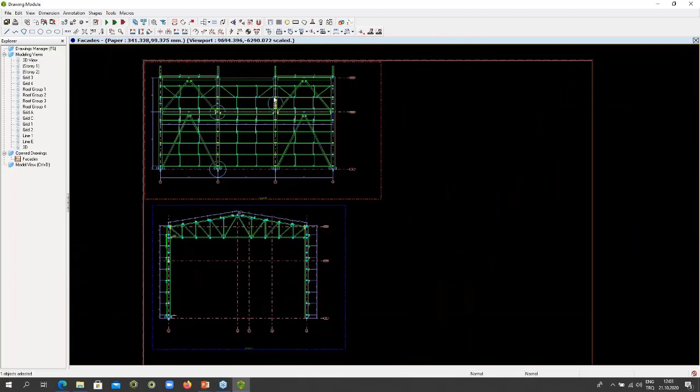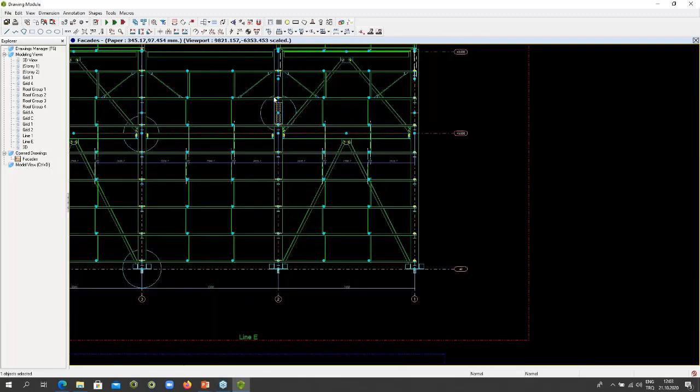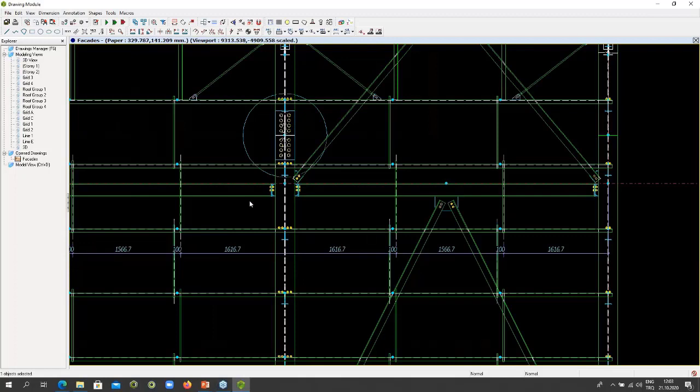And now the reason why we included the joint over here is that when we're going to detail these connections, we want not only to say that this is the detail, this is called splice 1, but we also want to show where else in the model the same connection exists. Because what we don't want to do is create thousands of these boxes all over. We just want to create 5 or 10 or 15 of these boxes in the model. And then we want the program to look for other places in the model which are similar to those places, and automatically find them, number them, and then give us the drawing accordingly.